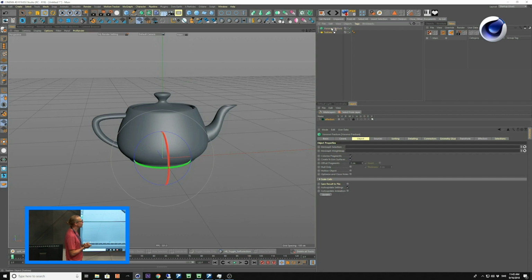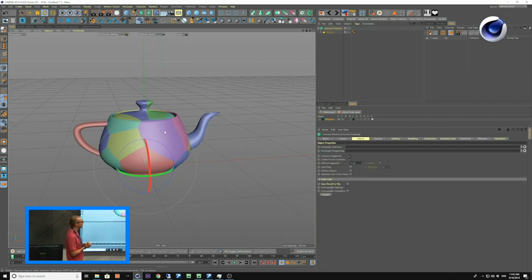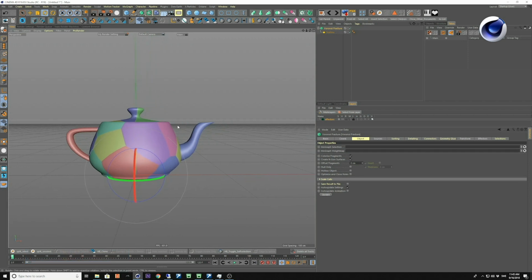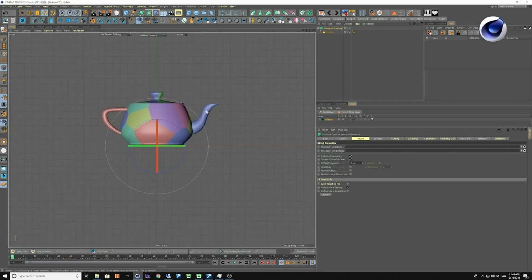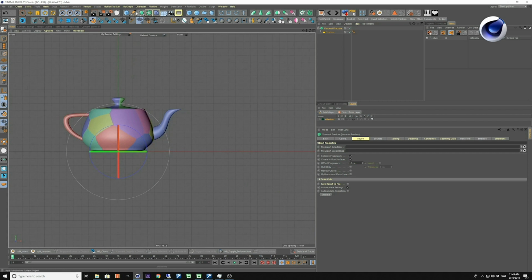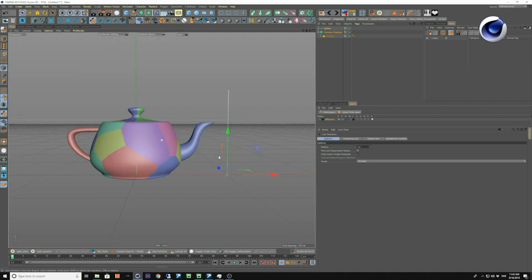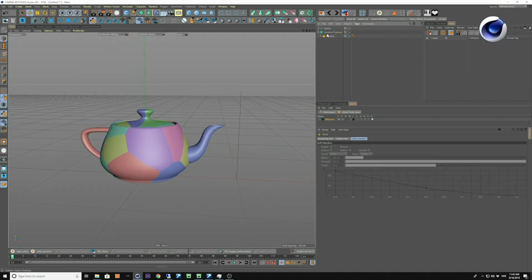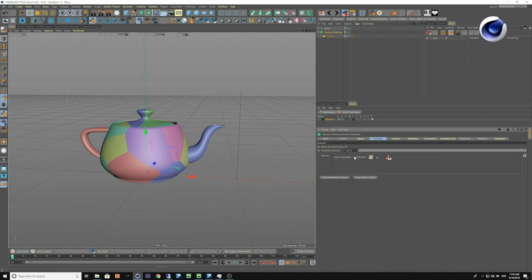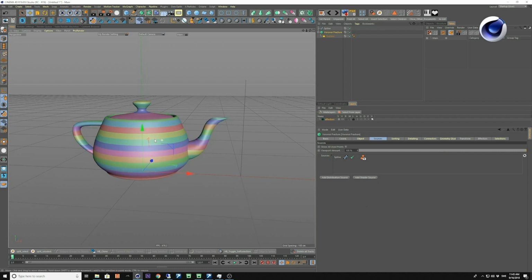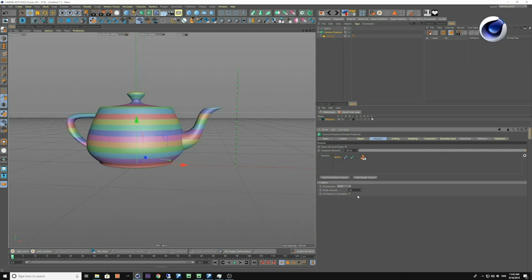And then I bring in Voronoi fracturing objects, and there you have the classic Voronoi fracturing look, which isn't very suitable when you're dealing with cars. However, in the source of the Voronoi fracture, you can feed almost anything. So after testing some stuff, I found out that you can put in a spline in the source object, and then the object is divided according to the spline, which is extremely flexible if you want to cut up geometry.